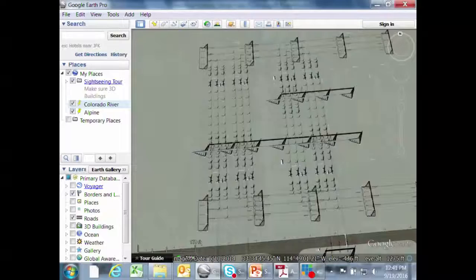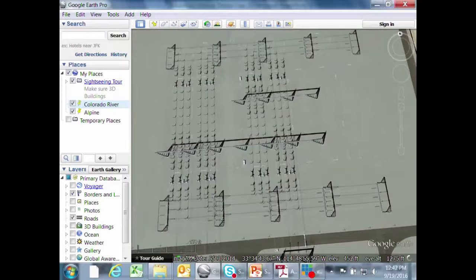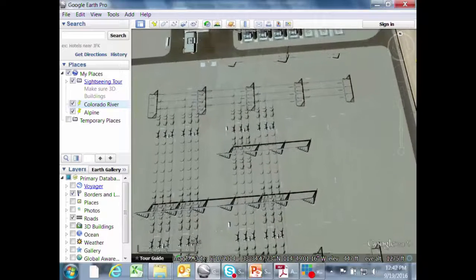Okay, there are ways that you could design this to avoid having to have such a tall structure, and Edison is looking at ways to try to reduce the cost of their substations. It's kind of complicated to show, but if you were to put the main buses right in the middle of the substation, use what's called a folded bus design, you could save a whole bunch of money in both steel and foundation costs on that. Anyway, for the rest of this, the steel that you see, kind of interesting.